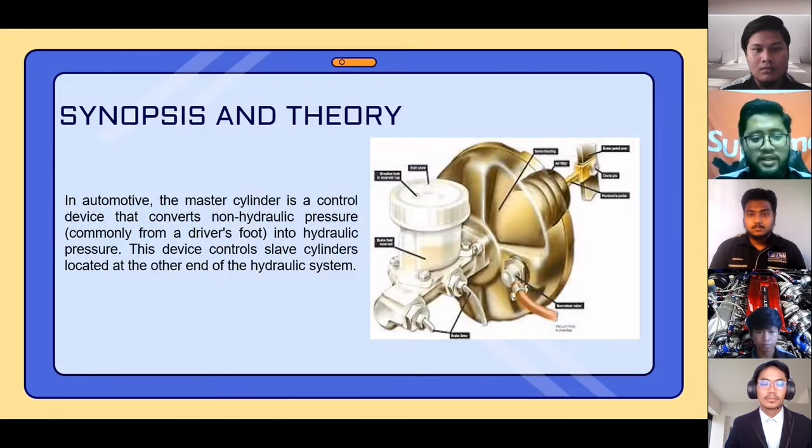The hydraulic pressure created by moving a piston inside the bore of the master cylinder toward the slave cylinder compresses the fluid evenly. But by varying the comparative surface area of the master cylinder or each slave cylinder, one can vary the amount of force and displacement applied to each slave relative to the amount of force and displacement applied to the master cylinder.